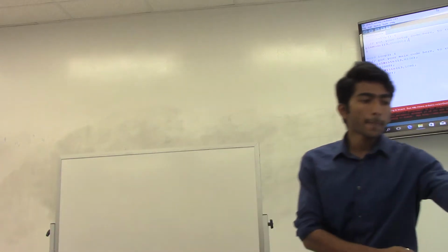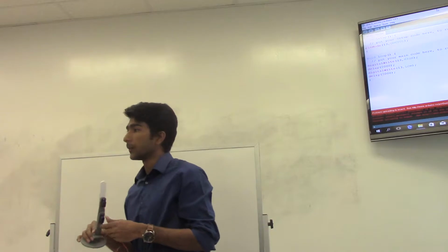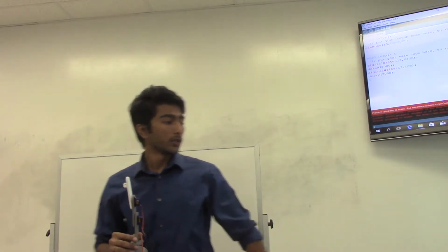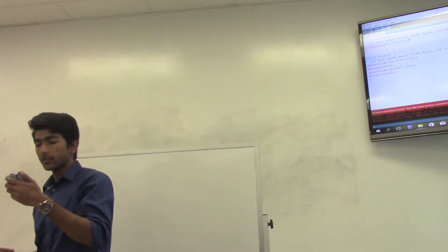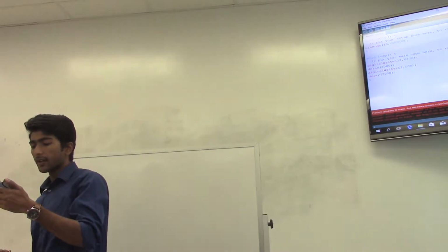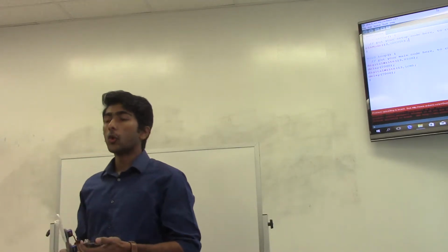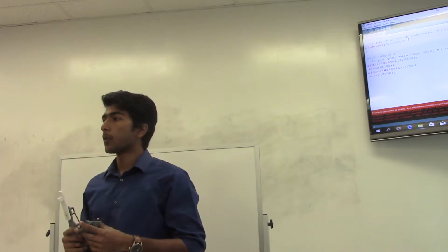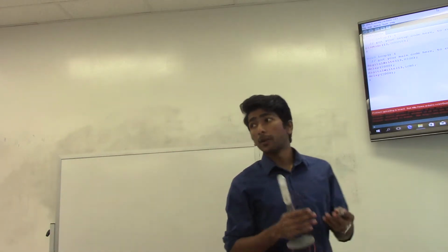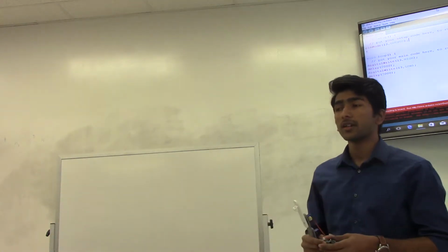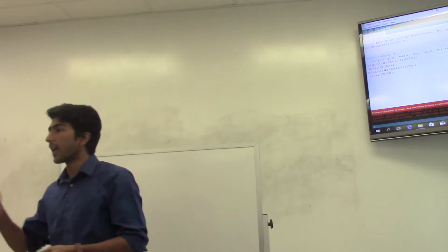So coming to the servo motors, we are going to use the digital pins on the Arduino kit. But if you take a close look at the digital pins, you will notice that pin number 11, 10, 9, 6, 5 and 3 has a tiny mark before the number. So those pins are actually called pulse width modulation pins. So they are digital pins, but they are also called as pulse width modulation pins, using which you can send a specific pulse of signal to set an angle of a servo motor.